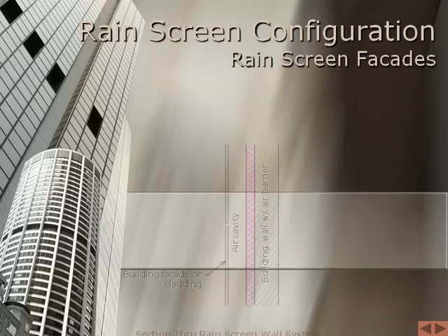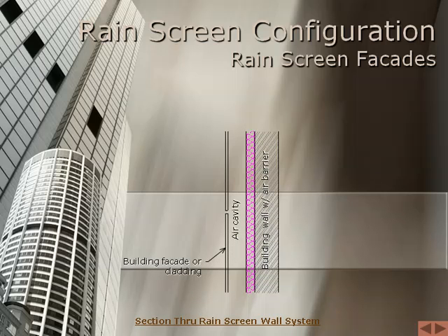The rain screen wall incorporates two wall layers separated by an airspace or hollow cavity. These component parts are the outer wall layer, usually considered as the decorative facade veneer, an airspace pressure equalized with the exterior environment, and the inner wall layer, considered as a structural backup or supporting wall. This layer contains structural load dispersing materials, thermal insulation, an air barrier, and if necessary, a vapor retarder. The inner layer of the walls needs to be structurally sound, airtight, and forms the air barrier, while the outer layer is vented to create pressure equalization to the outside.